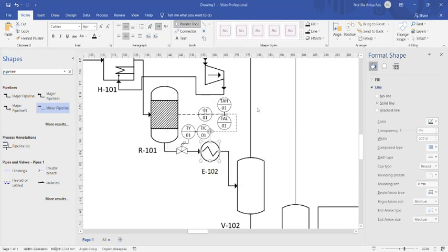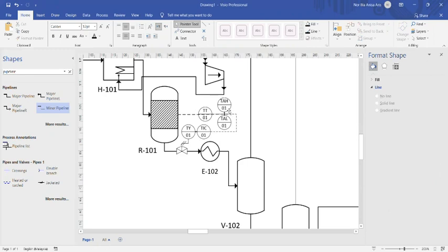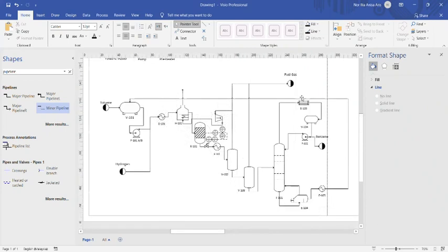So we have the temperature transmitter transmit the signal whether it reaches alarm low or alarm high, and then after that transmit the signal to the temperature indicator controller before it transfers to the temperature computer output to give a signal to a control valve whether it should increase the range or lower the range. So this is how we produce the process diagram.